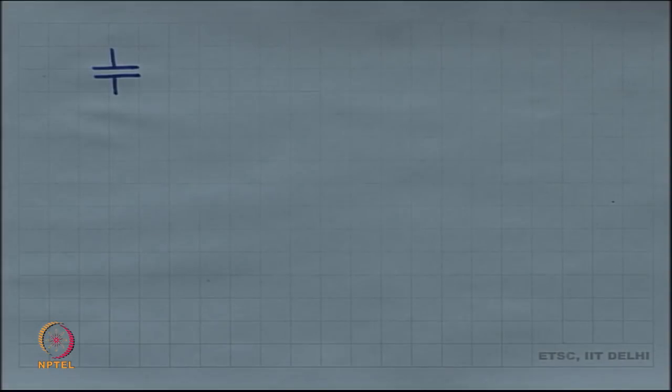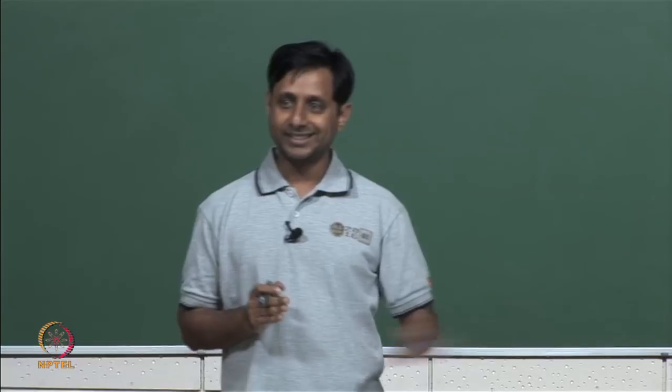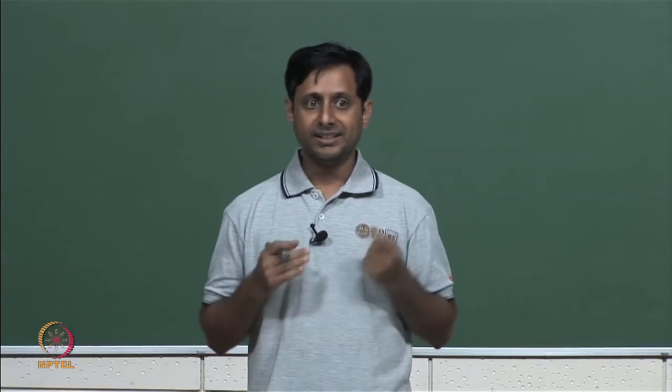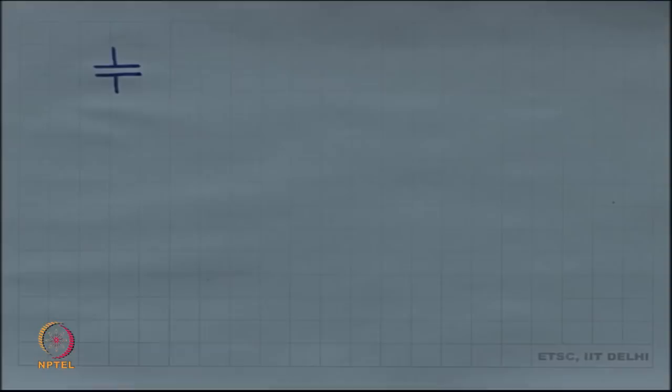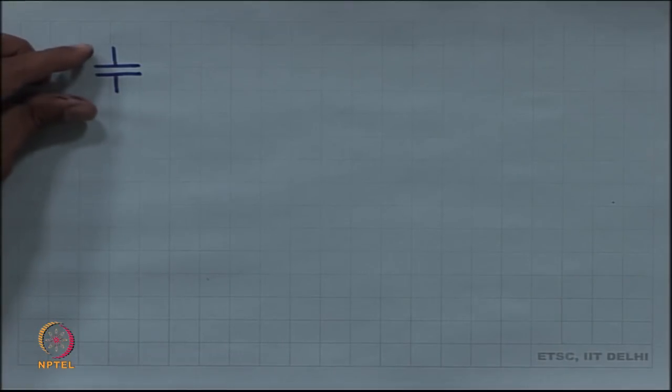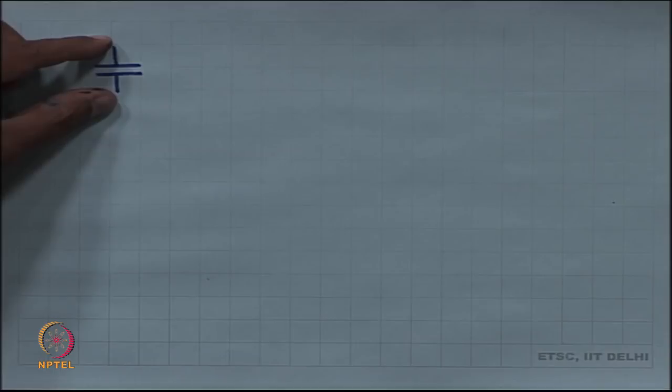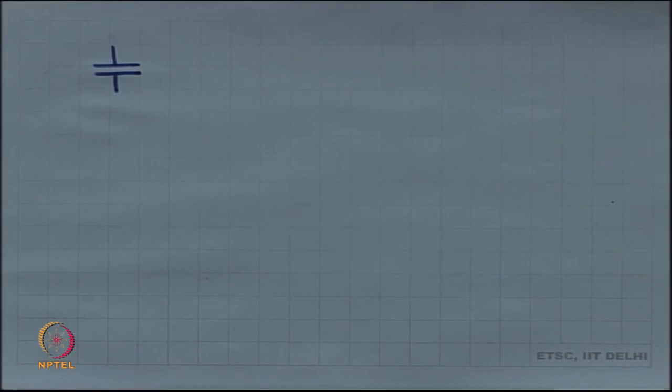In the most modern technologies, 28 nanometer, 22 nanometer, Intel is now at 16 nanometers, right. In these technologies, this dielectric, this gate dielectric is as thin as a few atoms, okay. It is really thin. Now, if you apply a large voltage over here, the dielectric is going to break down, and by breakdown what it means is that it is going to ionize, right. There is going to be some welding action.